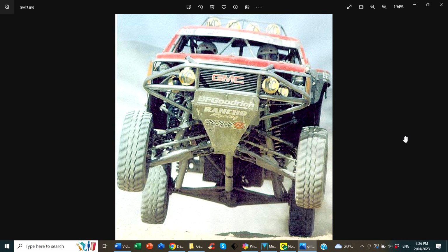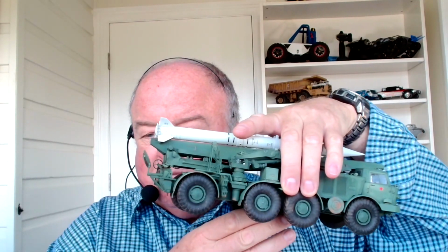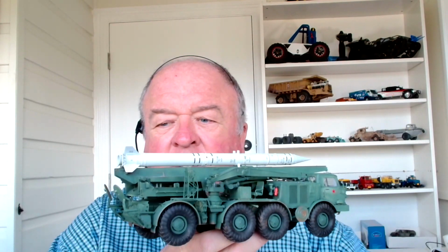And there are obvious safety issues as well. So the primary role of suspension is to keep the wheels on the ground. Now, you will have seen the frog, my friend the frog, from earlier videos. This is an example that suspension isn't always required. The centre two axles are not suspended. The fourth axle and the first axle are.